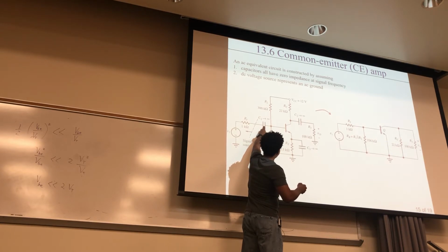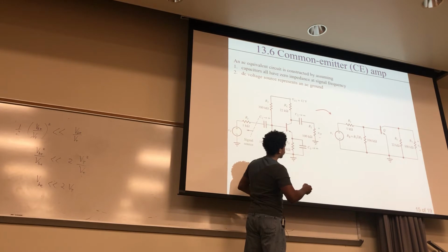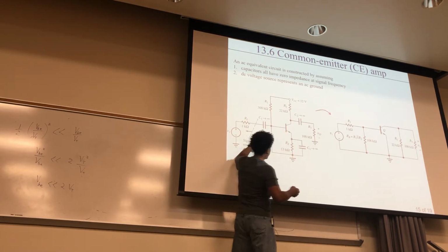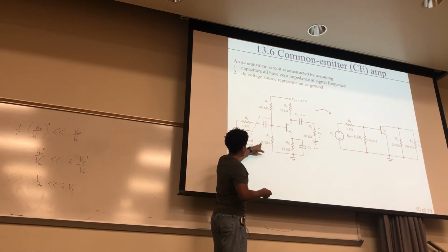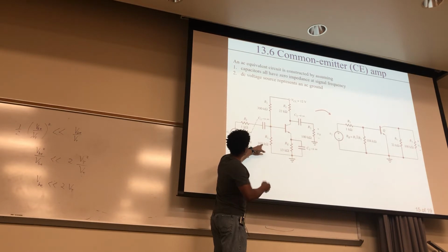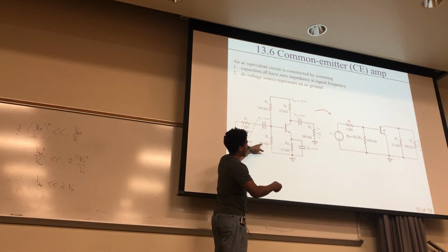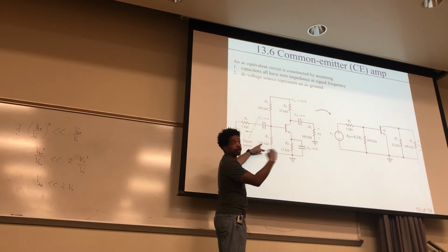So that's why you have this, right? And now you have this 104 kiloohms. What this came from is a 160 kiloohm resistor and this right here, 300 kiloohms. But if you put these two in parallel, then you get a smaller resistance going to ground, right? Because remember, this is going to ground right here, but this is also ground in terms of AC.